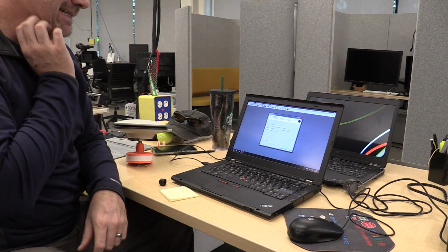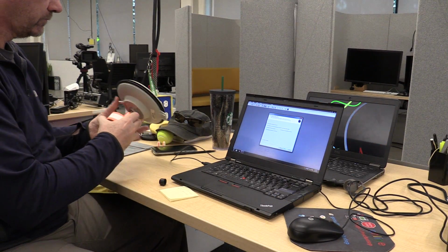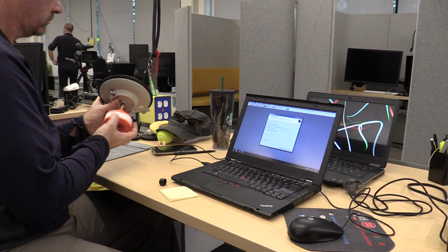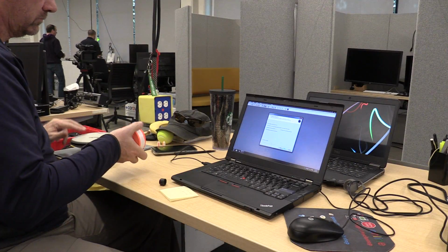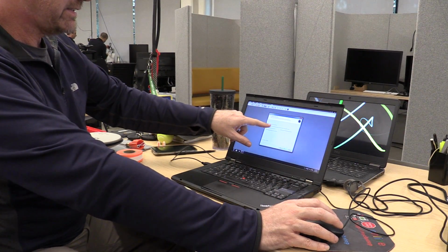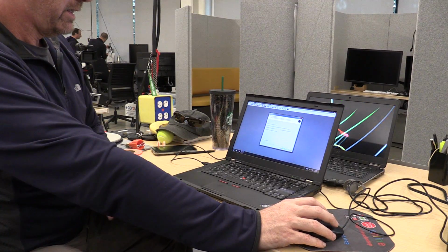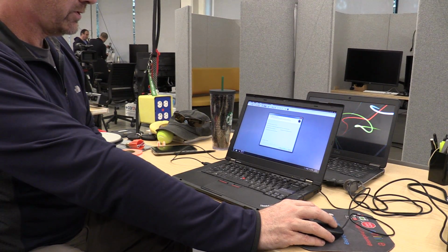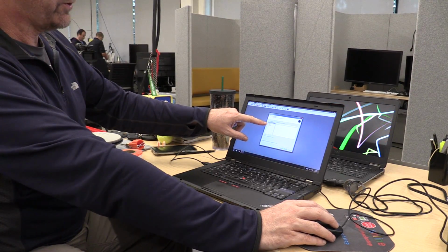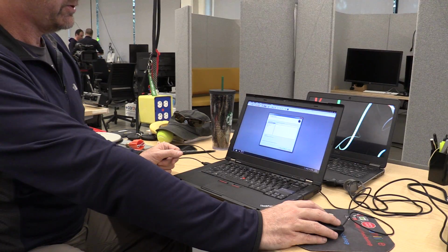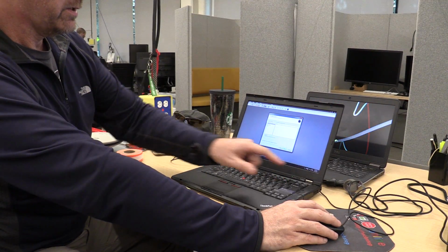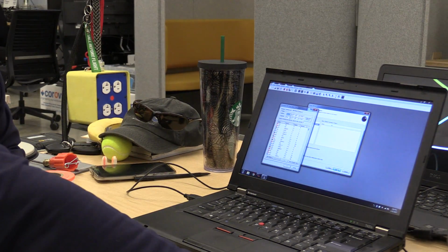All right, now, what's the next step? Enter antenna height. Select antenna measurement. Select appropriate antenna. Add base station data. So I would like to add base station data, and that's correct. Next, it asks me, do I want to add station data from a file that I already have, or do I want to download it? I tell the machine I want to download it. To do that, I must have an internet connection. All right, I say next.